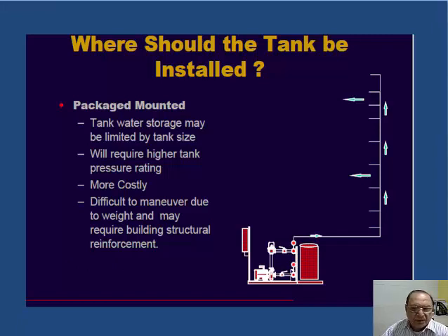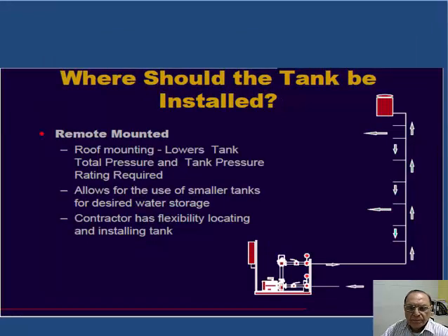The difference between those will be that the pressure drop will be taken from here and less pressure will be required, because that much friction and static head has already been lost. And it may give us a smaller tank because it is operating on the residual pressure and above it.